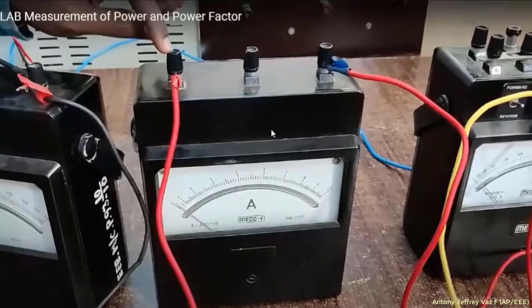In this experiment, we will be using up to 10 amperes. So what we are connecting here is the common point is connected here, and the other end of the ammeter, this 10 amps, is connected. If you need 20 amps, then this wire should be disconnected and connected to this position. So you should multiply the scale by 2. Then you will get a reading for the 20 amps ammeter.